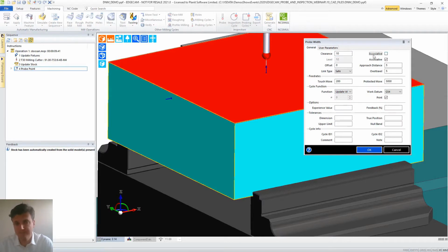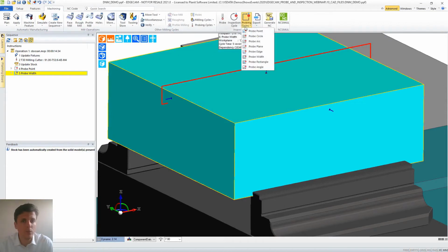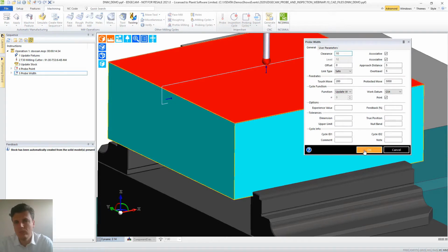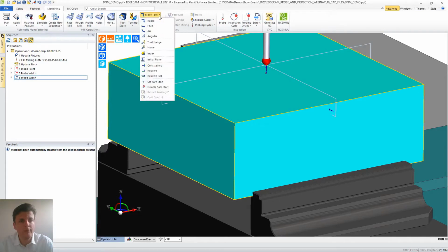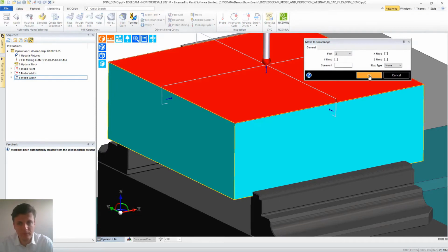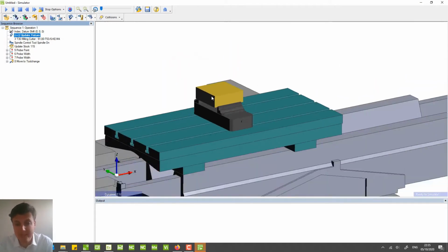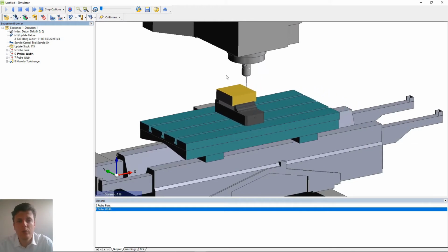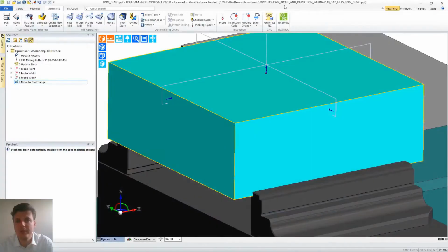Remember association. So toolpaths can be associated to the datum or to the feature. Create the other toolpath and then move to tool change. EDGECAM probing cycle, full simulation. So only the second touch is not simulated in the simulator, but that's based on your controller. Do you do 2 touches when you probe something, or only 1 touch? That's really up to you, but at the end of the day, this toolpath will be collision free.